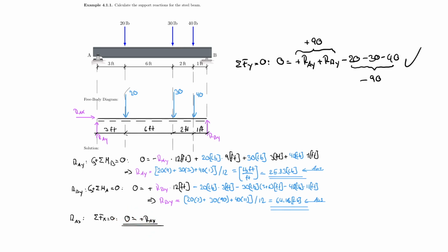And so one thing we want from you here is that you can identify where the horizontal support reaction is. So for example, if you would have placed the horizontal support reaction here, which sometimes I find students do in an exam, that is of course not correct, because here you have the roller and not the pin, and therefore you would lose points. So please understand that, and also understand how the equilibrium moment equations work as they are exemplified here. And then last but not least, understand that we have a moment divided by a lever arm, and that turns it back into a force. And I believe that completes this example, and we are ready for our next one.